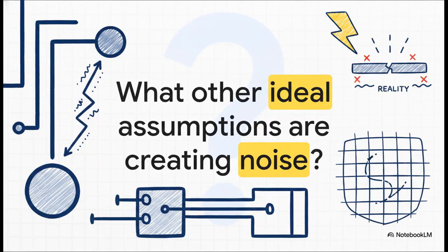Which brings us to our final thought for this explainer. It really makes you wonder, doesn't it? Once you finally accept the physical reality of impedance and completely abandon the myth of the 0-volt ground plane, how many other theoretical, textbook assumptions in your current systems need a desperate reality check? The physics literally never lie. Current will always find the path of least impedance. It's your job as the designer to dictate exactly what that path is.